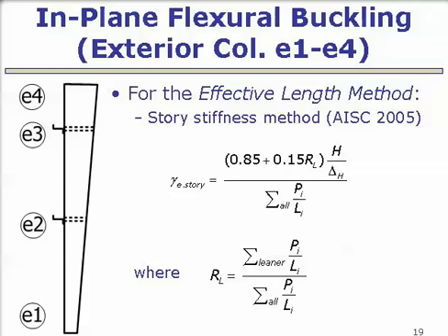If we're focused on this particular structure, what Yunduk showed you, it has the exterior tapered columns that are providing your lateral load resistance. All the interior columns are leaning columns. And so all the interior columns, when the frame sways, are tending to destabilize the structure in side sway. In the effective length method, we deal with that by looking at, well, how much can we ramp up any vertical load we have on the system in order to get to a point where we would be at a buckling load in side sway.